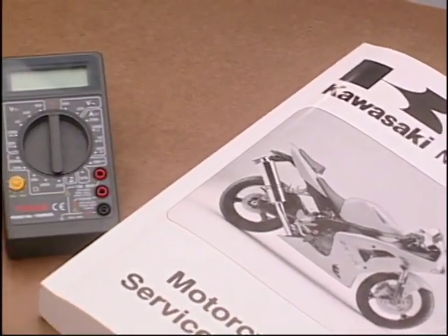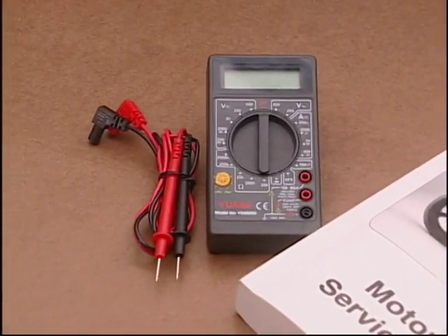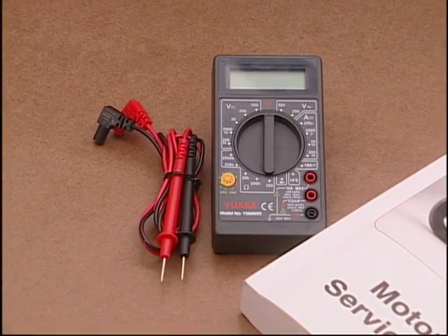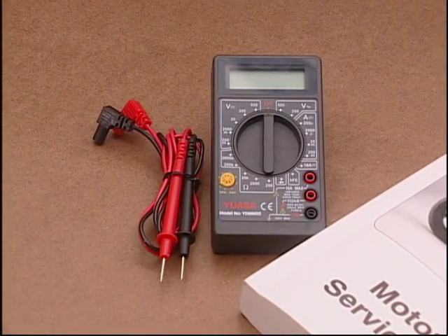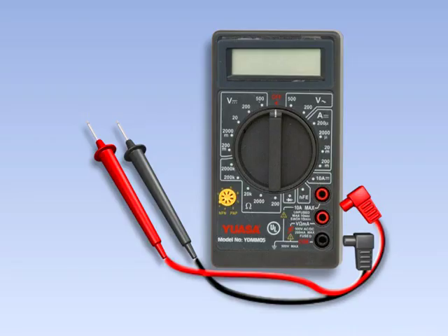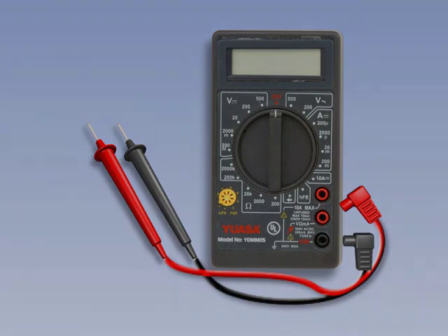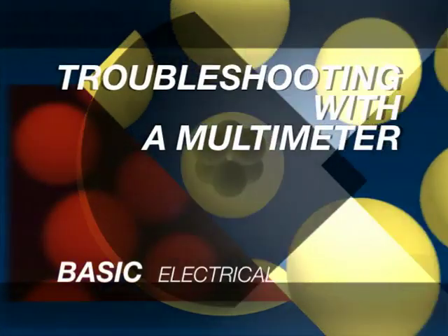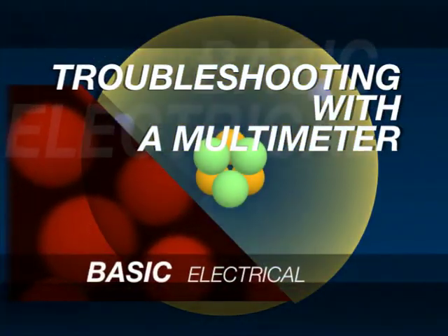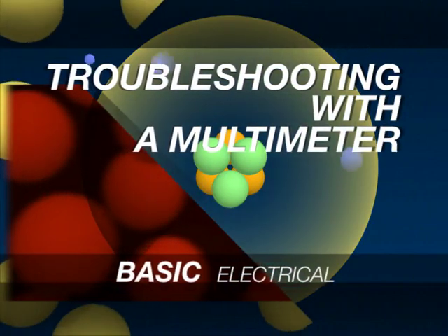Another essential tool is a multimeter, which is designed to measure units of electricity. Always consult the instructions included with the meter for proper operating procedures. The basic layout of a multimeter consists of a set of positive and negative test leads, a function selection switch, and a display screen. Most troubleshooting on a vehicle is done with the multimeter in either the DC voltage or resistance mode.